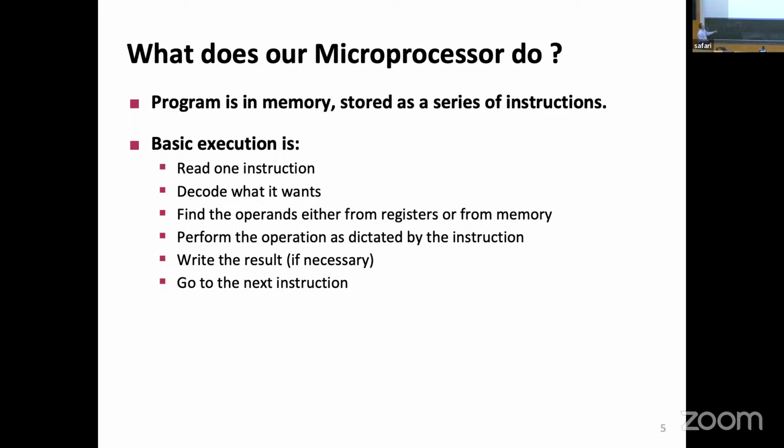Well, the program counter points to a place in the data memory, and corresponding to that address, there is the instruction, it comes out. We realize that the instruction has different bits telling it what to do. There are special bits that say, hey, this is an R-type instruction. R-type means that data is found in a register file, or register array, something like that. It has 3 addresses. 2 of them are for reading. So this is address 1, this is address 2. So I can find 2 operands in the register file.